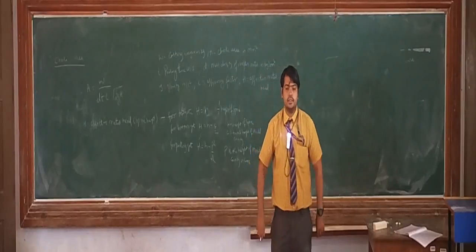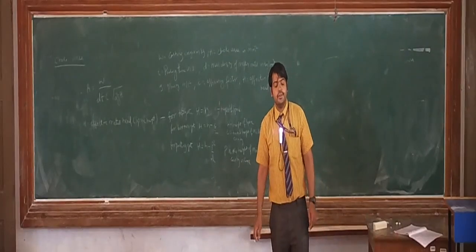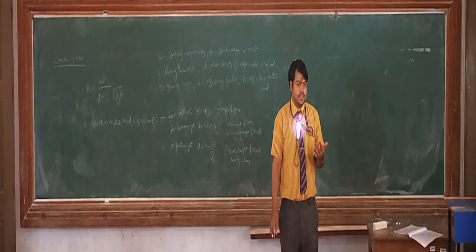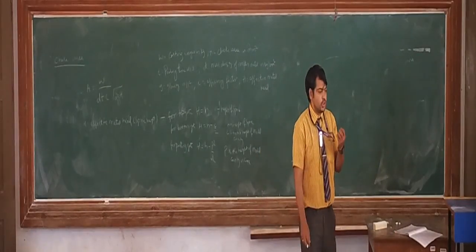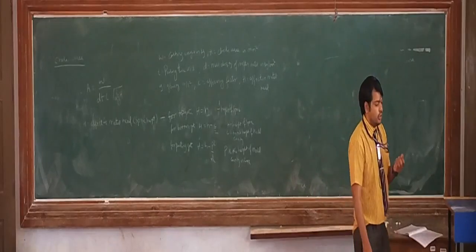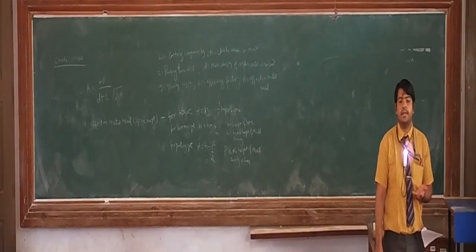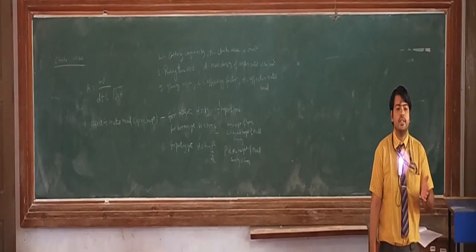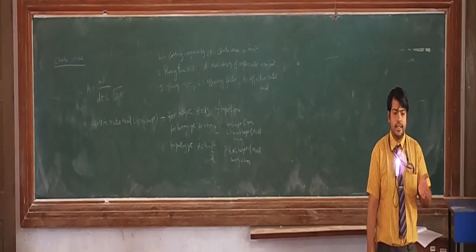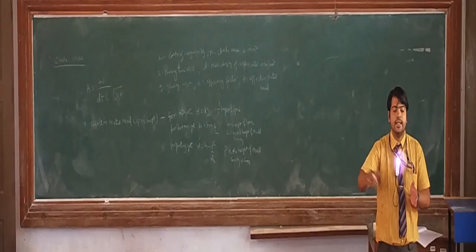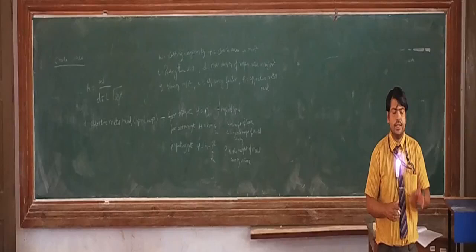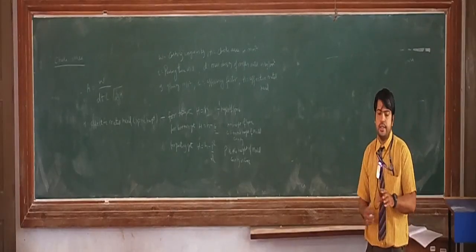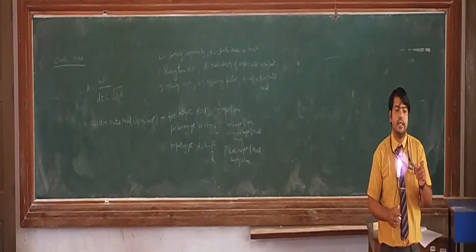In the last class, at the beginning of this particular unit, we have discussed about the gating system, and there I have explained something called as a choke. Okay. So here, how to find the area of the choke? What is this choke exactly? Let us understand first. In order to regulate the velocity of the molten metal, which is coming from pouring basin to the sprue, then it has to move to the runner, and from there it is going to the mold cavity. The velocity of this molten metal has to be regulated, and this is what is being done by using a particular small part in the runner called as choke.